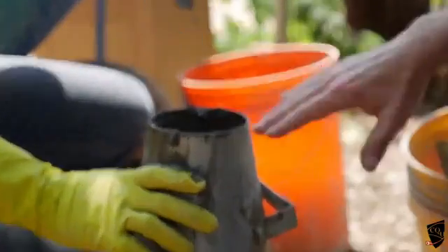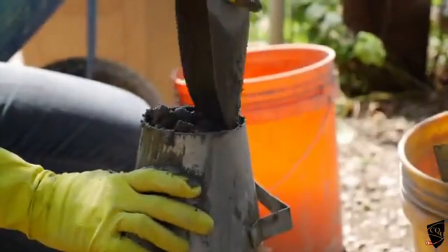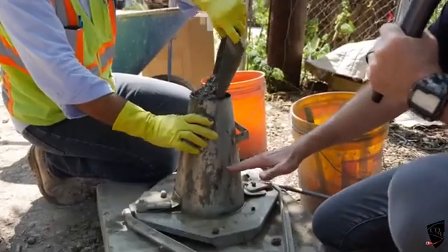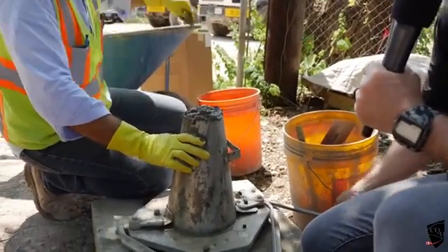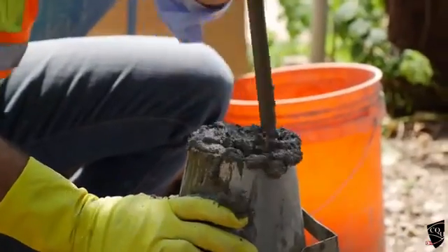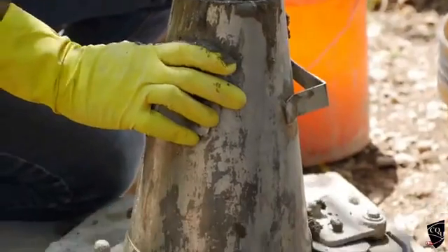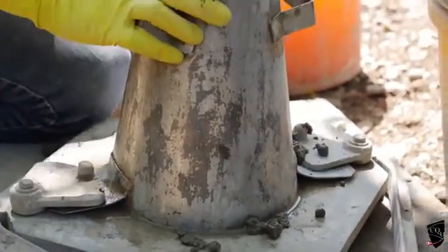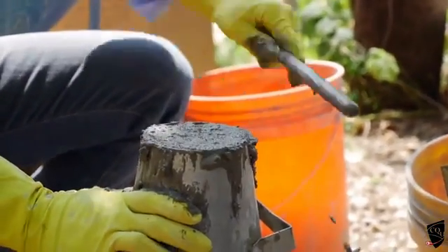When he gets this thing all the way filled, we're going to pull the cone away and see how much that concrete falls. You can see he's doing this in lifts, about 3 or 4 lifts, and each time he's using a piece of rebar. He's got a fancy rod here, but you could use a piece of rebar to do this. We're making sure all the air is out. You can see some bubbles coming out of the bottom, making sure that concrete's in there nice and good. Then he's going to level it off and pull this out. Okay, so that's it. Looking good, he's saying.